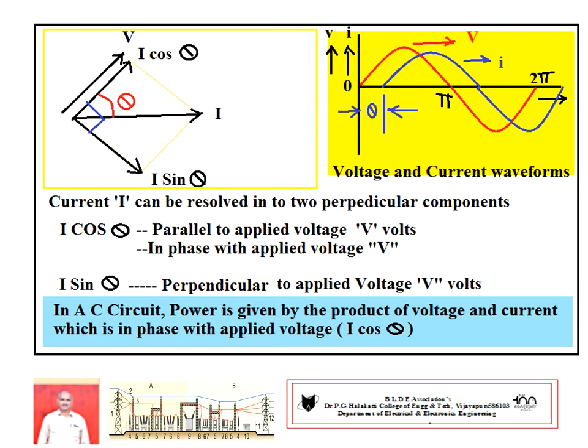Draw the voltage and current waveforms. You see the right side circuit, that is the voltage and current waveforms. You take the voltage as reference. It starts from 0, from 0 to pi. It is red colored. The waveform is voltage. As compared to voltage, the minus sign means lag. Current lags the applied voltage by an angle theta. But theta is not 0 and less than 90 degrees. Be careful, you draw less than 90 degrees, 30 degrees, 40 degrees and so on.